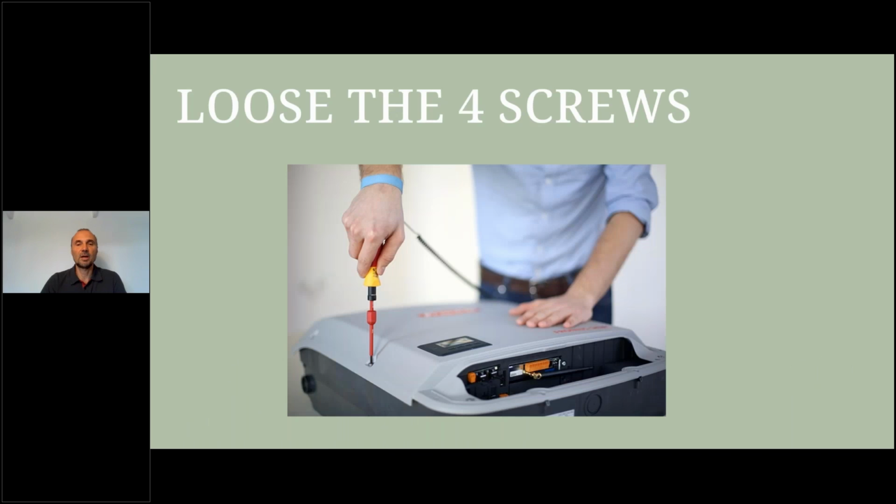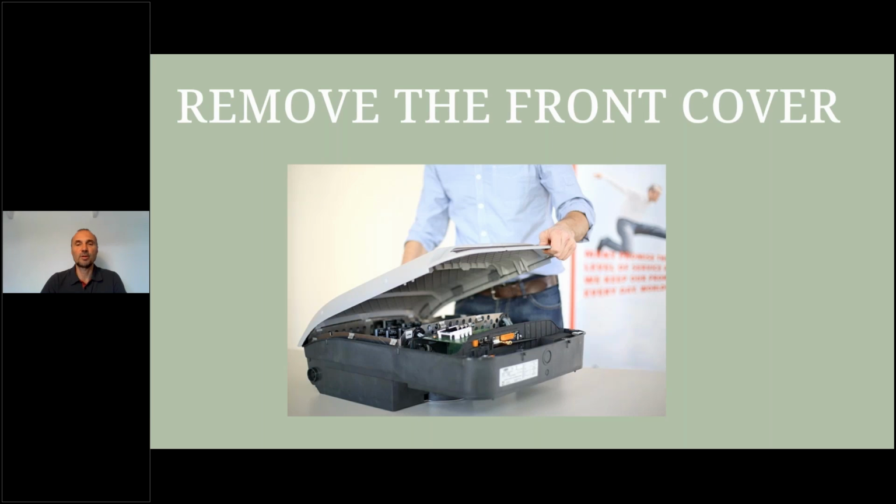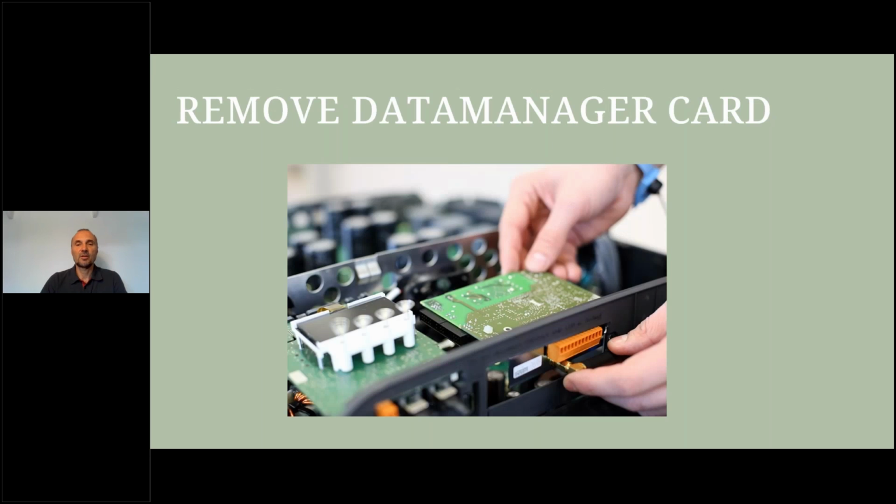For the replacement of a data manager and display card, I have a few pictures here to show you how it will look like. You see here the opening of the 4 screws in the front cover to open the front cover. You see as well the data manager card. The data manager card is just fixed with 1 screw in the front.